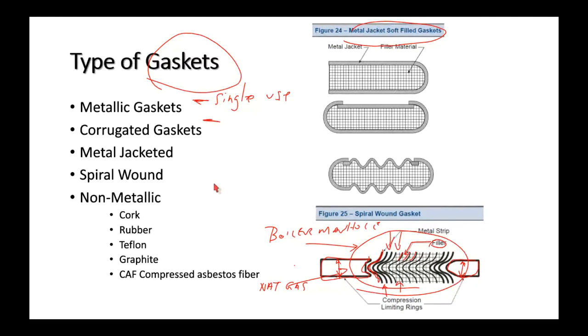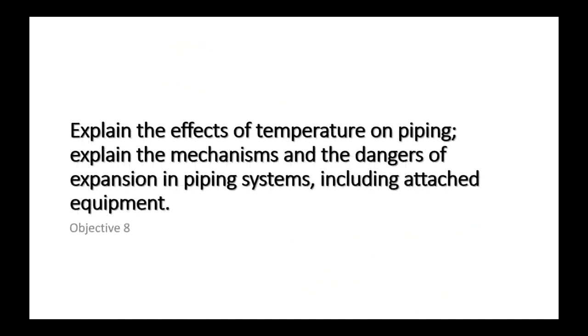And so I would go by the gaskets that were piled up, and I would have a utility knife in my pocket, and I would cut them in half. And every once in a while, one of the engineers in the plant would go, "Well, what are you doing? We were going to reuse them." And I'd say, "Really? You were going to risk your life for a $2 gasket?" So, yeah, do not reuse gaskets.